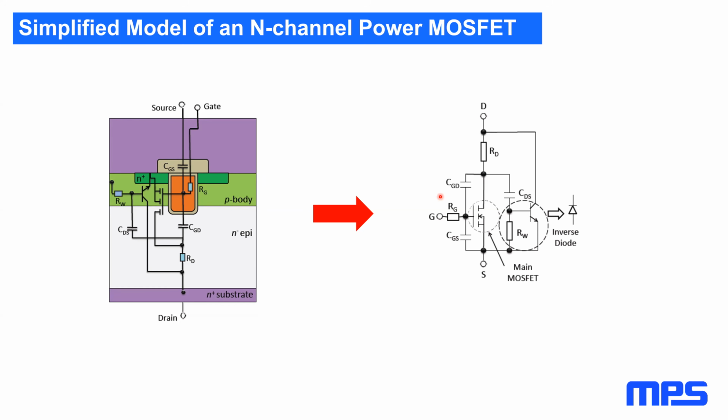What a gate driver IC with a Miller clamp does is it drives the gate, let's say at turn off, from a voltage down to 0 volts for an N-channel MOSFET with a limited current capability, series resistance, for example. Once it gets it turned off, to prevent false turn on from any activity that might happen on the drain, then you really want to hold the gate down hard, not with a weak resistance. So that's what the Miller clamp does.